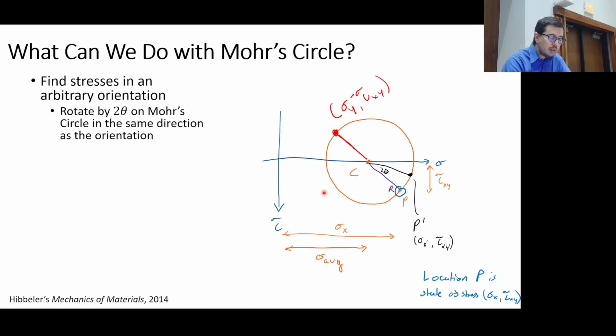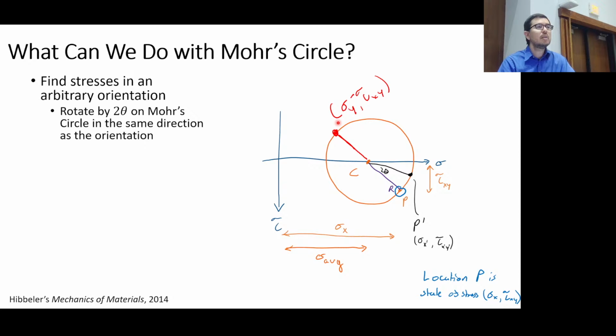Now, we would have already drawn the Mohr circle, and some interesting things happen. If you go 180 degrees, that's like going 90 degrees on the material element. And so if you went 90 degrees on the element, you would go 180 degrees like this, right? You see these two lines are supposed to be collinear. This one right here and this one right here are supposed to be collinear. If you go all the way around, 90 degrees from sigma x, okay, is sigma y. Right? We've now done this.